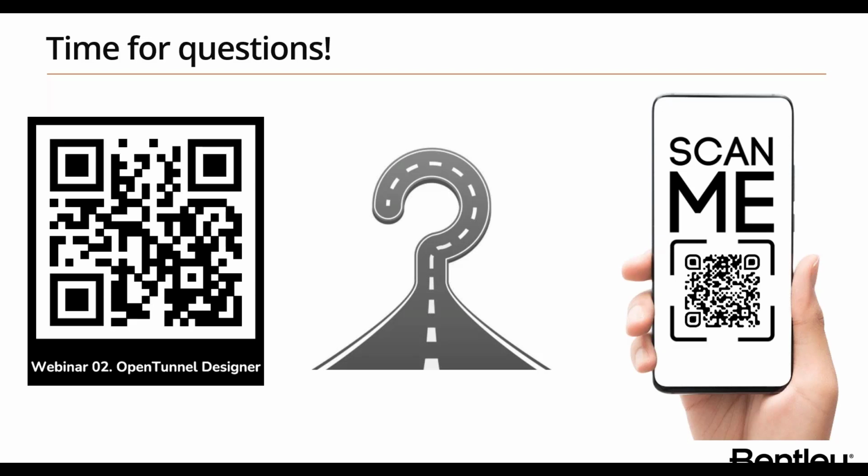Excellent. Third question: are all the additional elements such as interfaces and others necessary for the calculation directly added and managed in Plaxis? The interfaces are automatically created. What we are not sending at this moment are the loads and also the stages. So we are not creating the stages. Basically, we are creating only the geometry at this moment in time, and the user will add additional loads over that geometry, then go to mesh and then to construction stages to create those stages. But for future versions, we hope we'll have this implemented also.